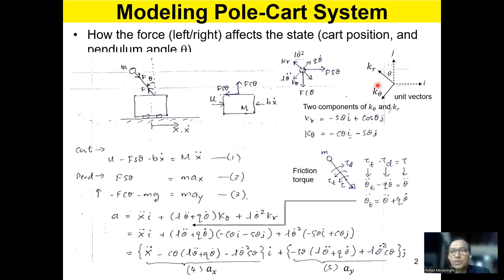So if you refer to this diagram over here of the unit vectors, we can resolve kr, for example, into i and j. So the horizontal component of kr is, this is unit length 1, times sine theta, and it is in the negative direction. You can see it over here, negative sine theta i. Then the vertical component is cos theta j. Can you see that? Cos theta. This s theta is actually sine theta. C means cos. Okay. So that is the ij representation of kr.